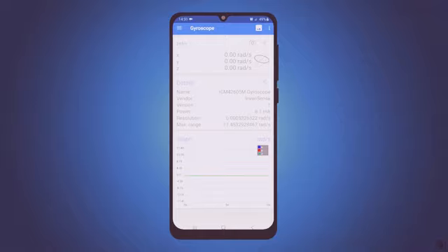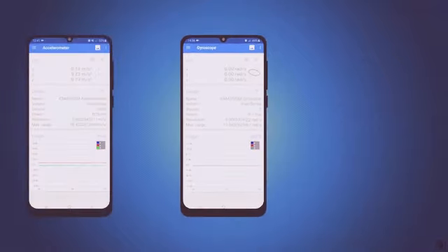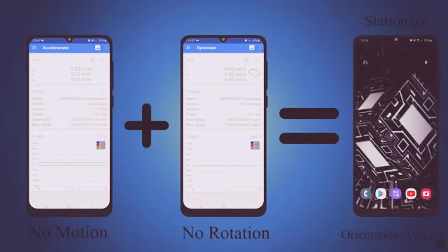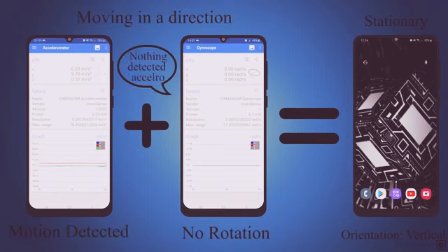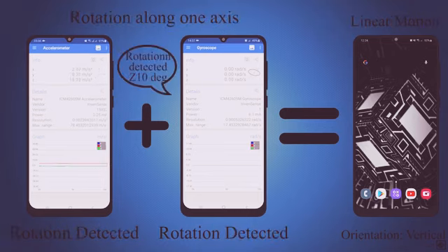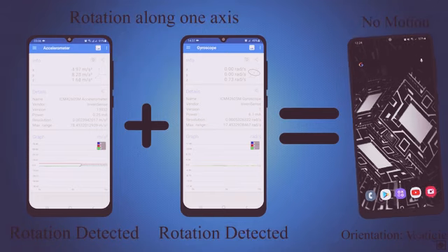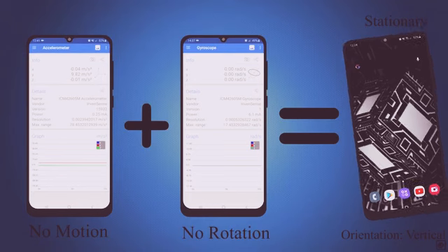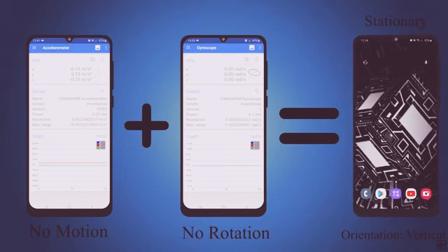Due to these uncertainties of accelerometers and gyroscopes, they apply a principle called sensor fusion, in which they combine data of different sensors to achieve a much more certain outcome. We know that when in motion, the accelerometer will actually detect the perceived gravity, not the actual gravity or acceleration. By using the rotational information from the gyroscope, we can estimate what the actual gravity vector should be. Also, we can subtract it from the perceived gravity vector to calculate the true acceleration.